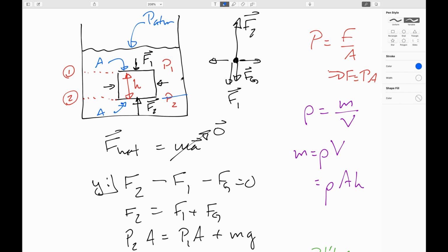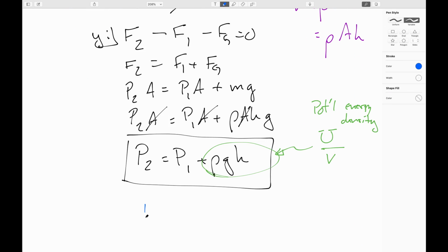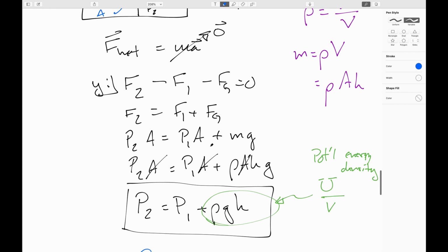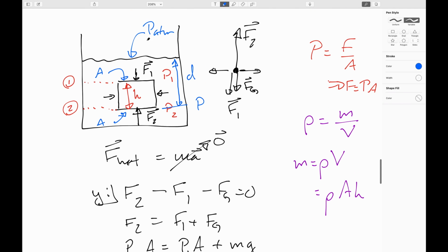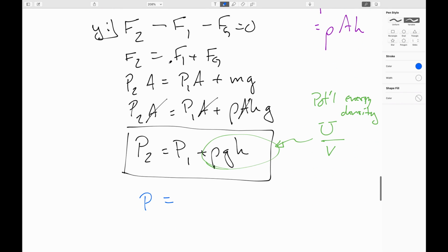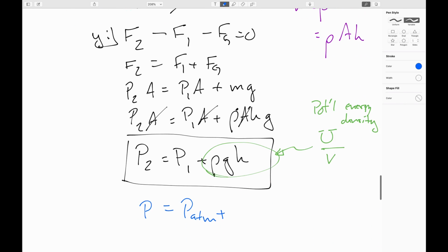So we can just say, if I want to know the pressure down at that point there, we can look at this depth D here. And then I can rewrite this and say, if we called it the pressure at that depth P, the pressure at that depth is just P. And now instead of picking this height, this reference pressure here, I'll pick this reference pressure here, which is atmospheric pressure, which I know, plus rho times G times this height here, D.